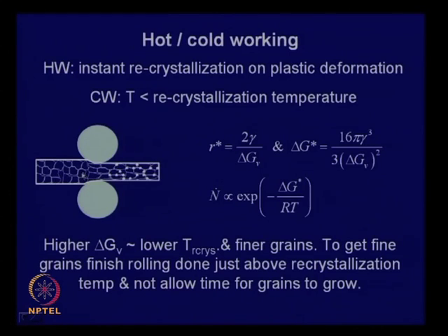So, the initial bulk of the deformation of steel is given in the austenitic state, around a temperature of, let us say, 1150 degree centigrade. That is the place where you give this large deformation, and after deformation, the new grains which form will grow with time. So, the key to getting a fine grain structure is to control this.